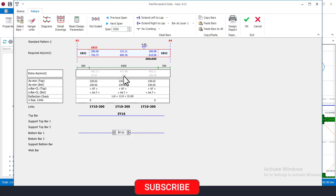You can see that the area of steel here is showing 3.94, which is very, very minimal, very small. And if there is any kind of issue in construction, this beam is very prone to fail because the area that is already there is very small. So right now, always take your area of steel around here, extra area of steel around here. For now that you are a young engineer, always take your area of steel around here to not be less than 75. Okay, 75 millimeter square.